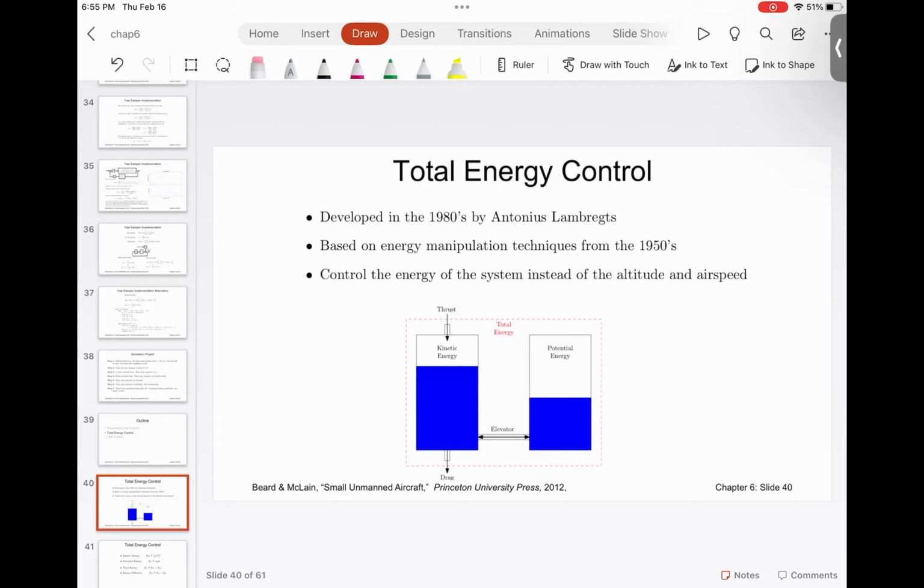Theta is dependent on kd, and omega n is dependent on kp. Once you tune kd, theta gets changed. Once you tune kp, omega n gets changed. Essentially you place the poles of the transfer function, or you tune the eigenvalues of the state space model, to wherever you want.